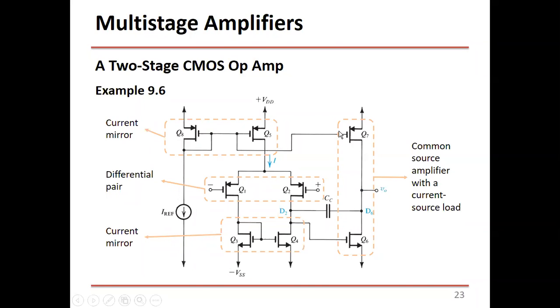Okay. So this operational amplifier or differential amplifier has two stages. The first stage is a differential pair, consisting of these two transistors. They are a PMOS differential pair. Whenever you see two transistors face to face with a tail connected from the source, with a tail current, then we assume this is a differential pair. Okay, with two inputs as well.